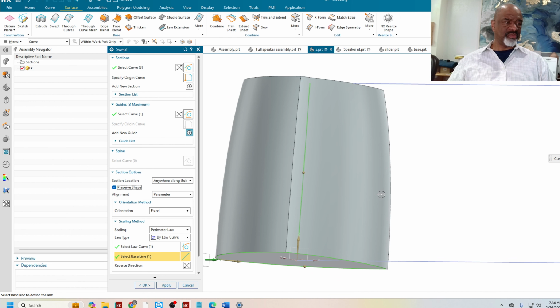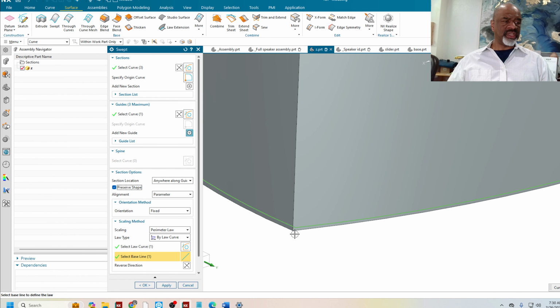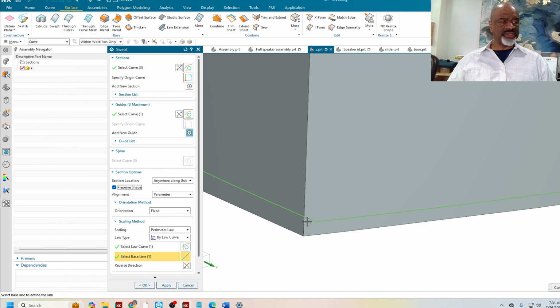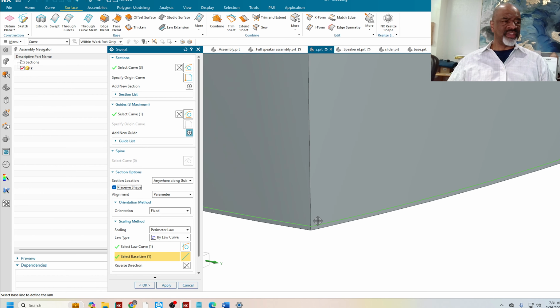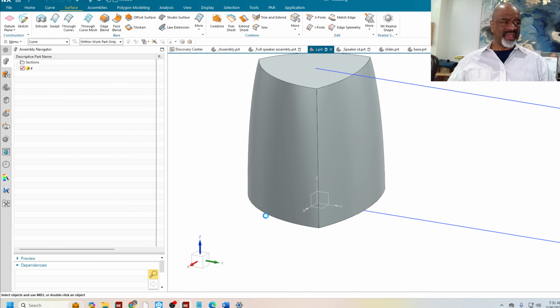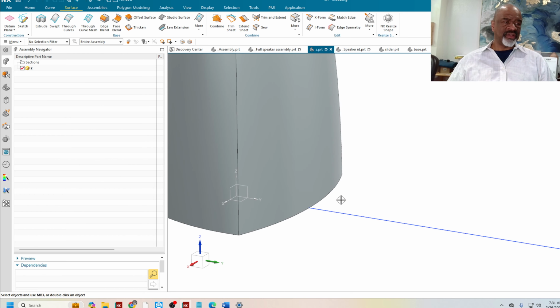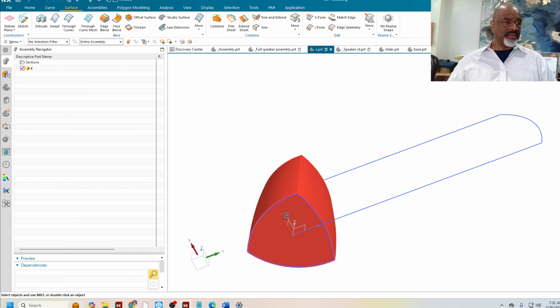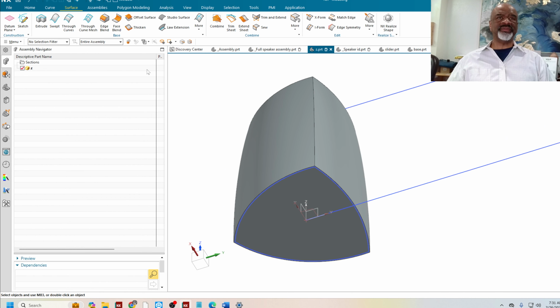Preserve shape is a really important thing to understand. What you can also see is that my surface is not really conforming to the curve or the section that I started with. Why not? Because my law curve is based on 32. I just approximated that. And the perimeter of these entities is not exactly 32. So if I want it to match up, I need to go back and I need to do a measurement.